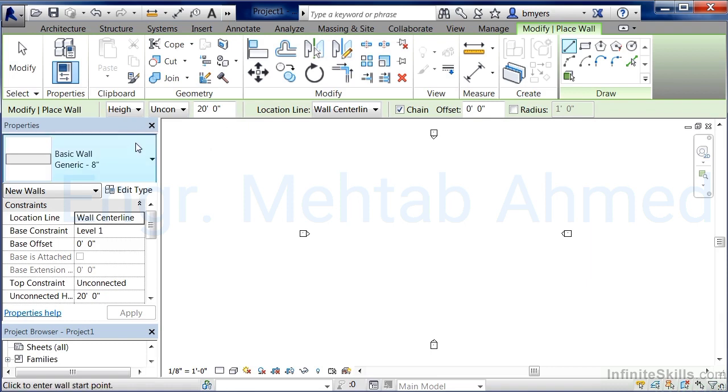For instance, it now has a pull-down menu asking us questions related to the depth or the height of our wall. There's a menu here that's going to allow us to click inside of it, highlight the information, and if we wanted to type in a different height for our wall, we could do it. The options bar also allows us to check or uncheck different options in order to turn on and turn off different functions. So the options bar allows us to change different options associated with individual commands.